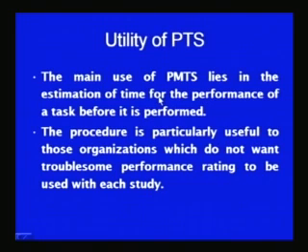So, here in this method, the method which is to be followed for producing a particular component is broken down in the data sheet or record sheet in terms of the basic human motions required for performing the job, and then time values for those basic human motions are obtained from the predetermined time values in the data bank.